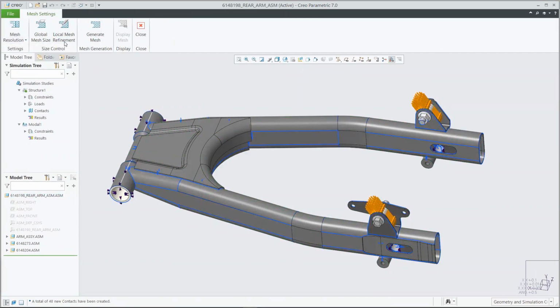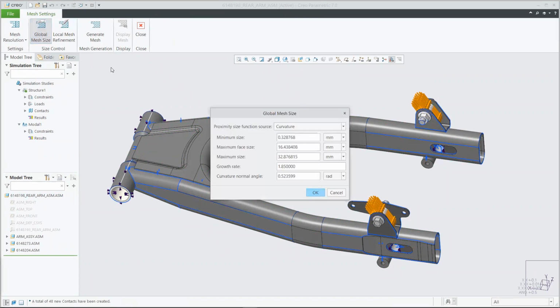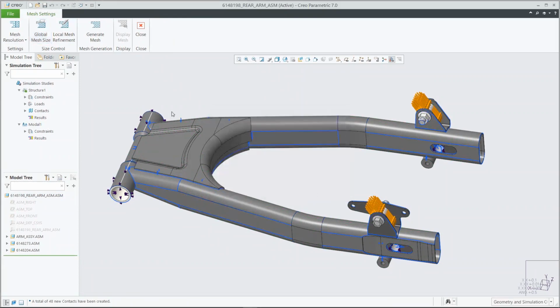This is very straightforward to do. Essentially, you'll have a first initial resolution that you could lay out, but around this as well, if you do want a little bit more control over this, you could go through and lay out the global mesh sizes, just really allowing you to get to the different details that you want within that mesh resolution.